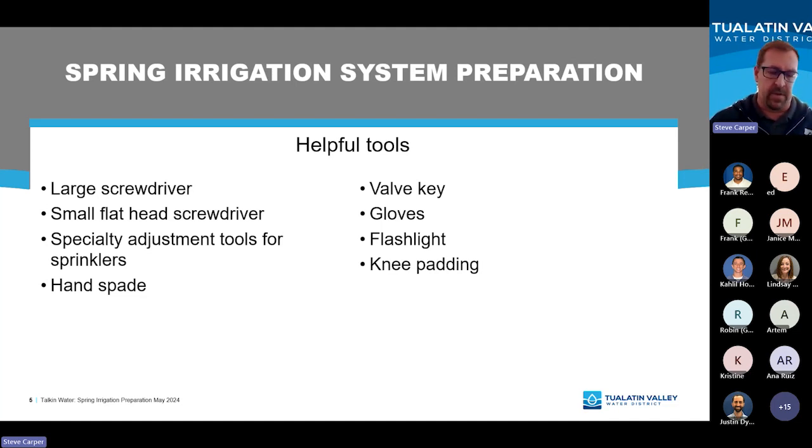We're generally looking for the green top valve boxes, and over the course of a season, the dirt can get in there and kind of make things difficult to access. So a large screwdriver can help you provide some leverage and get those boxes open quickly and easily, safely.